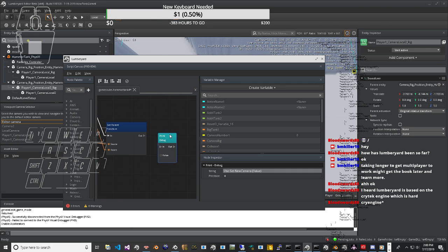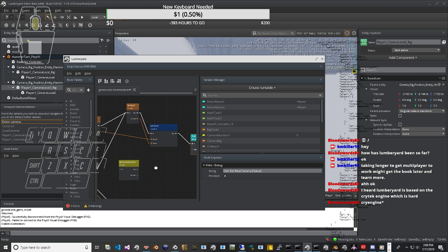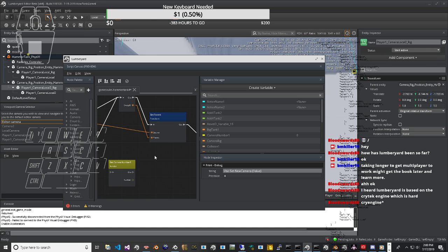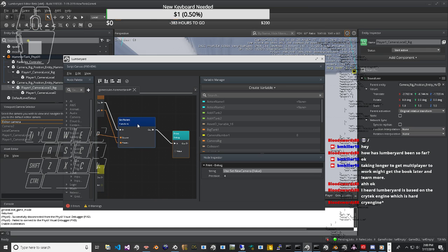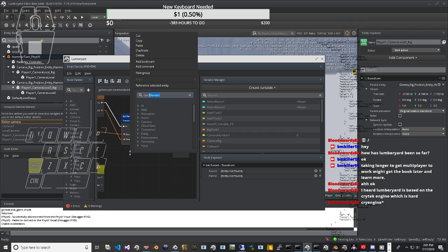As a final comment, let me say that I am somewhat dismayed that the magic formula does not account for any variation of the lateral force with speed. Intuitively, the forces generated at high speeds must be greater than the forces at low speed with the same slip angles. However, the literature sometimes explicitly, and sometimes by sin of omission, states that the magic formula doesn't deal with it. One of the reasons is that, experimentally, effects of speed are extremely difficult to separate from effects of temperature.